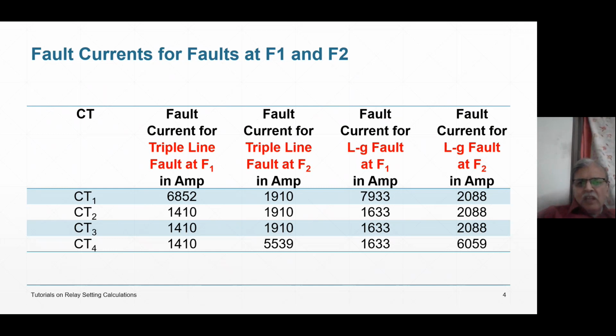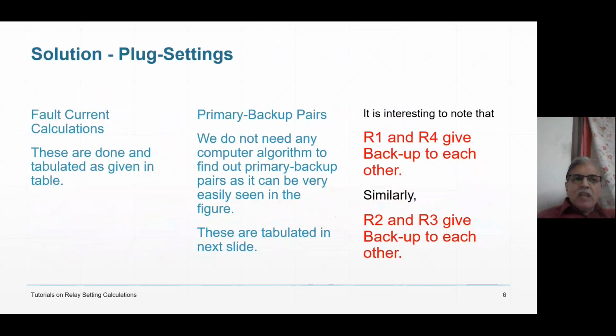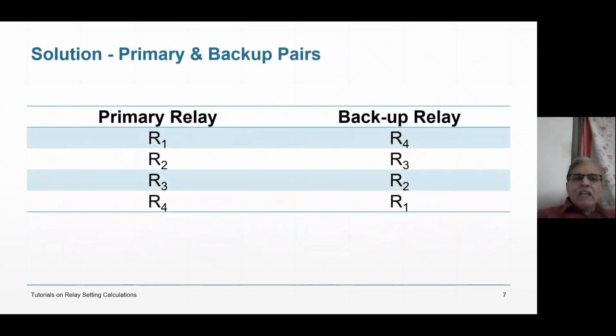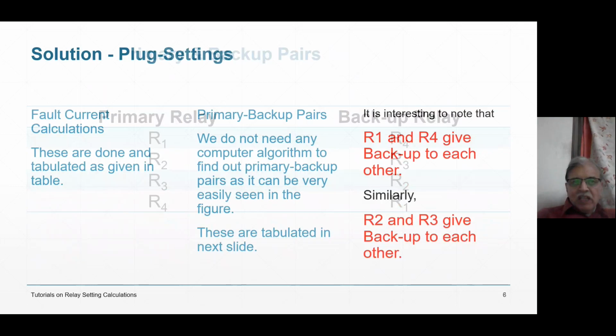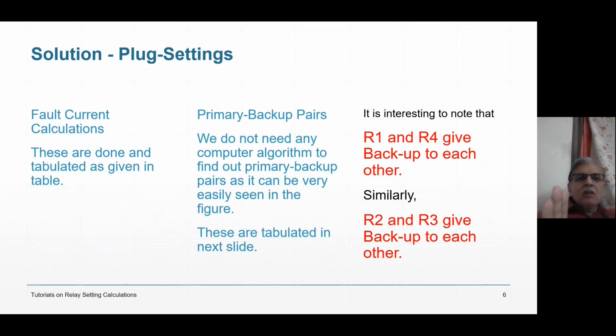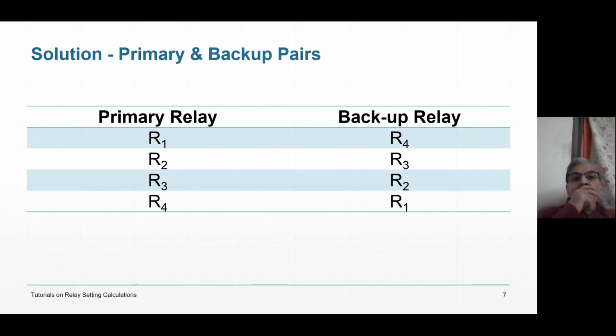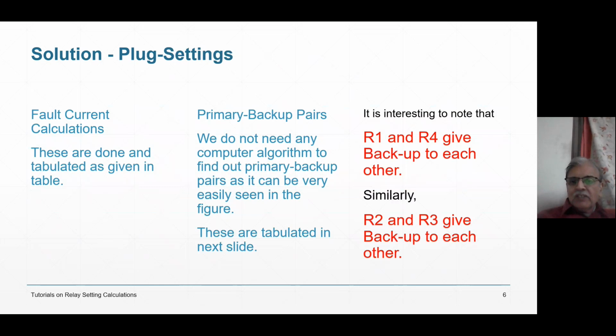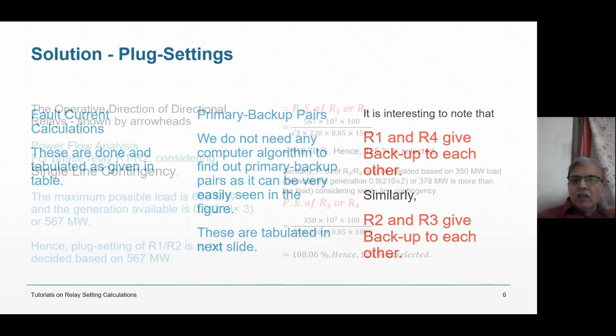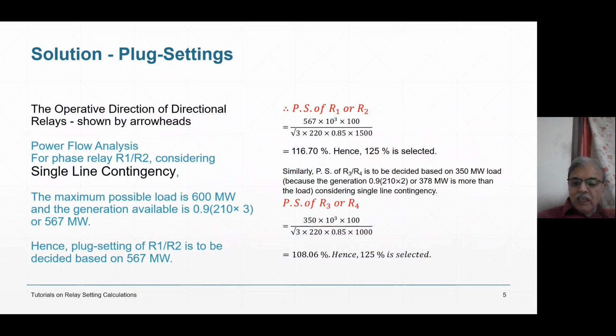This is possible. Such a system is possible. So fault current analysis you will have to do for all the possible contingencies, and that I have done. And based on that, now I am finding out the time setting, my dear friend. Plug settings I have done. But before I find out the time settings, this is what I have done. Plug settings for R1, R2, R3, that I have done.